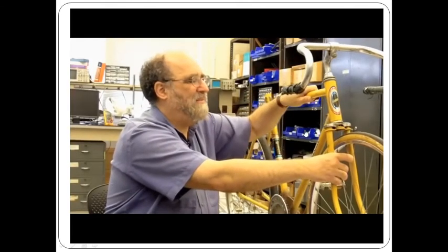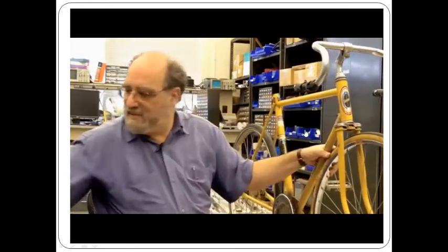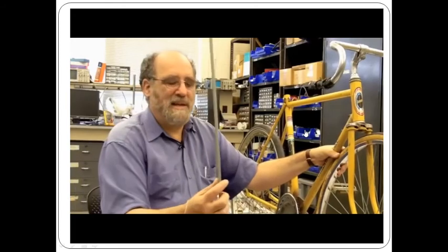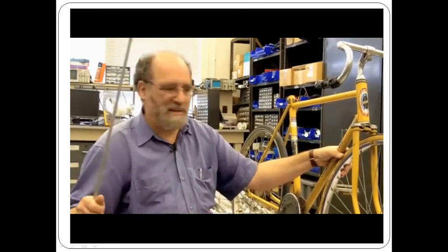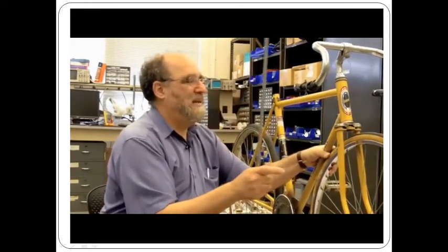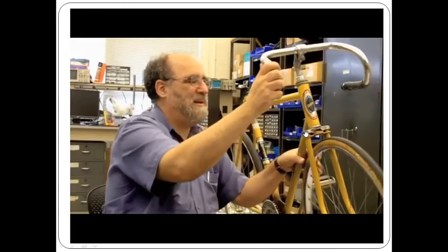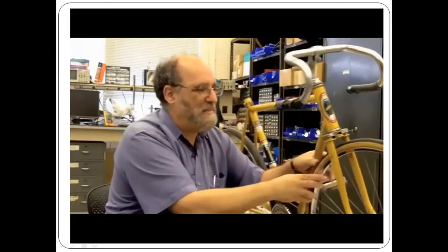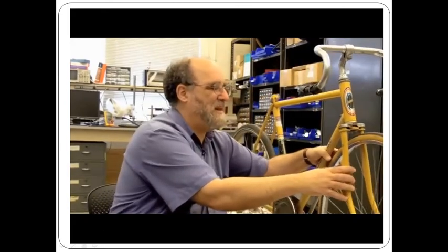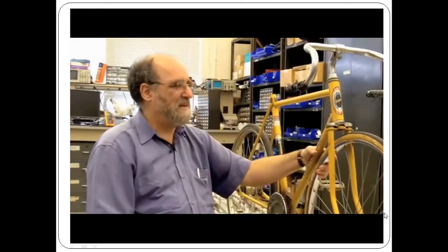And when the bicycle falls, this one tends to fall faster, just like if a stick falls and the stick is shorter, it falls faster than a longer stick. So this front mass falls faster than the rear mass, but they're connected to each other by the steering axis. So in its attempt to fall faster, it causes steering. And that's what we think is the primary mechanism of stability of this TMS, this gyro-free and trail-free bicycle.